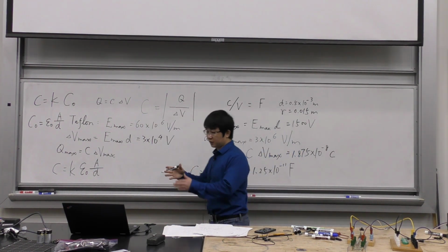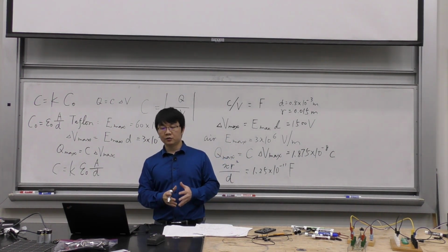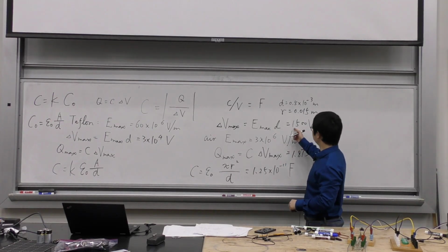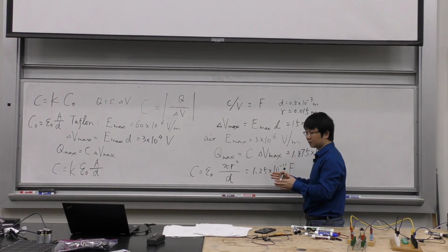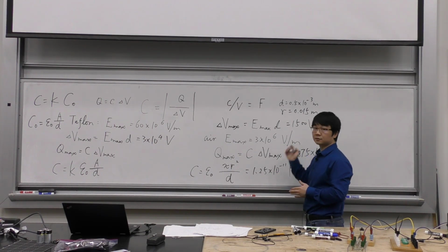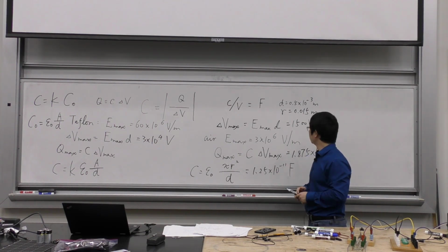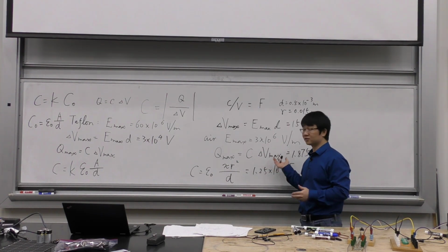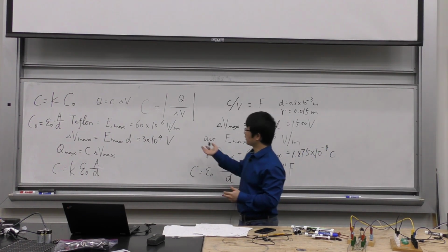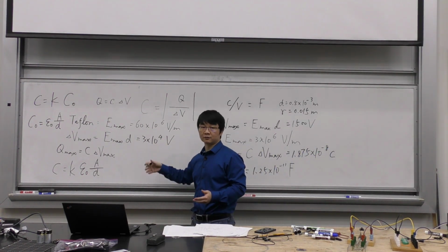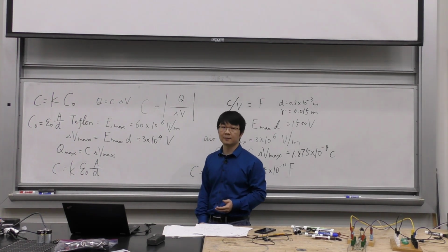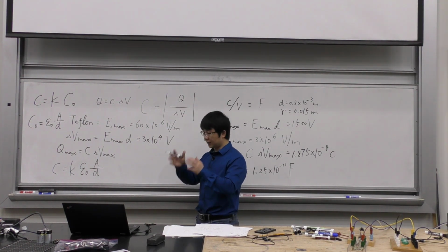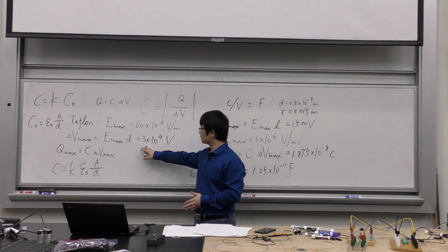Okay? So now if you put Teflon between these two plates, you can use this capacitor at a voltage larger than this, right? Like 1500, if you only have air between them, you cannot use it higher than 1500. Like if you want to connect it to a 2000 volt voltage source, no, it's not going to work. It's going to damage this capacitor. But if you put Teflon between them, yeah, that's fine. 2000, fine. 5000, fine. Right? You can still use that. So that's one reason, right? By adding this Teflon, the dielectric, in this capacitor, you can raise the maximum voltage it can be connected to.